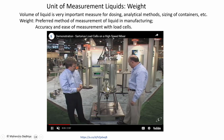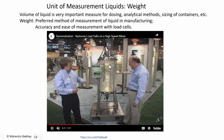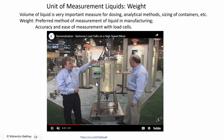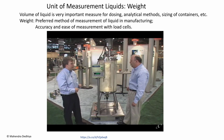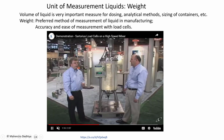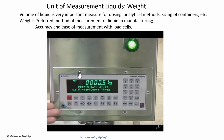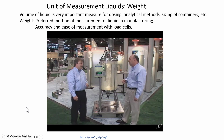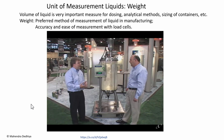So once we mix it, you will see liquid moving, and we cannot measure the volume of the liquid, but the weight of the liquid on the load cell remains constant. And it will show 152.6 to 152.7 kilos. You can tare the weight to 0, and now you can add mass to it. In this case, 0.5 kilo is displayed as a tare weight, and this is very accurate for 1500 kilo max. This cannot be done by measurement of volume in production scale. So this is the advantage of load cells and weight measurement.